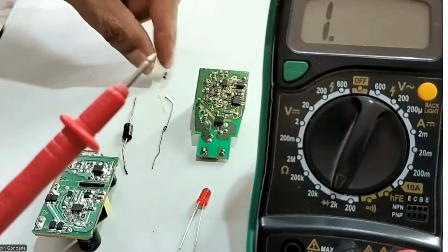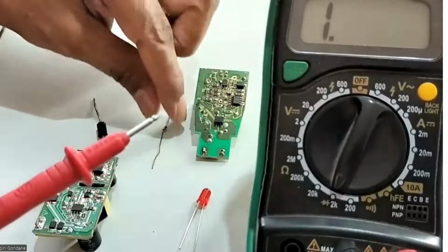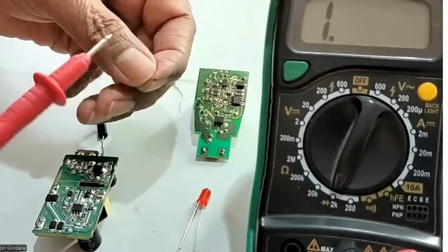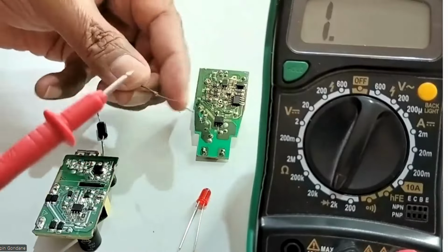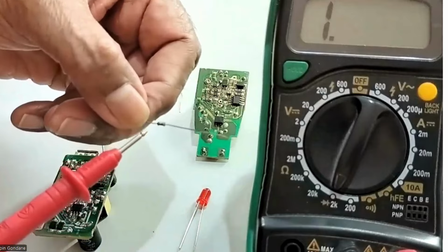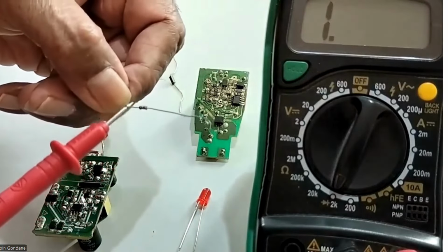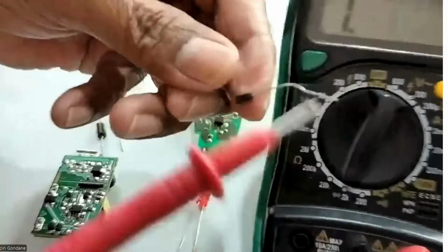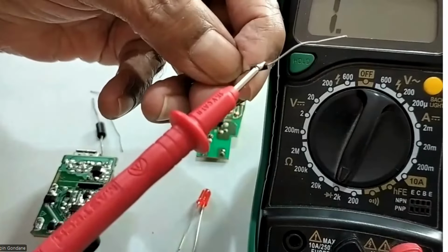So this is one diode. This is another diode. Same process. Let it be this Zener diode also. So what do you mean by that? It works on forward bias, and it will not work on reverse bias. The same thing here. But how will you find out the anode and cathode in this? A marking will be there. That is the cathode. Here also you have a marking, but in black diodes the marking will be a white or silver line.